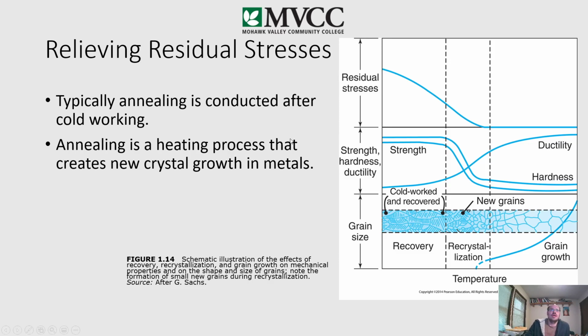So one way to do that is relieve stresses. And again, we'll talk about this in more detail when we get to heat treatments. But relieving these residual stresses is done through what's called annealing. So this is typically conducted after cold working because they want to relieve those stresses. So what you do is you put it back in the oven, and what this is showing over here is